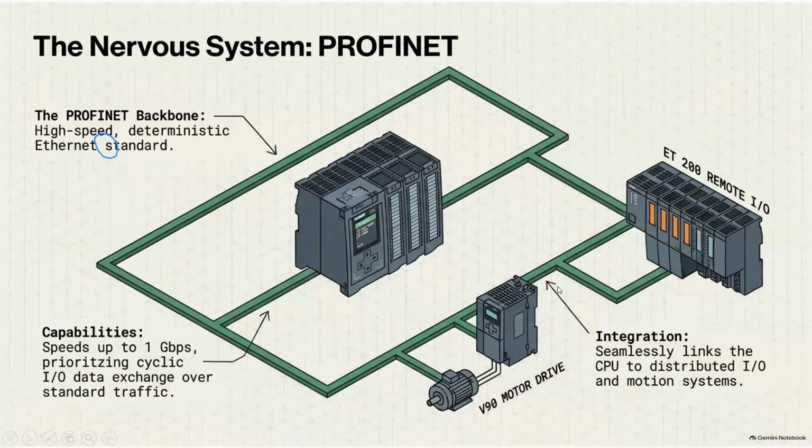This is a tricky part we face everywhere in the industry, where VFDs or a few IO devices are there, and they might not have the same communication protocol that the main system has. In such cases, there will be an additional IO interface circuit. That is the way these model numbers will vary.